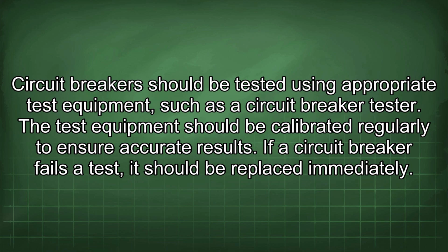Circuit breakers should be tested using appropriate test equipment, such as a circuit breaker tester. The test equipment should be calibrated regularly to ensure accurate results. If a circuit breaker fails a test, it should be replaced immediately.